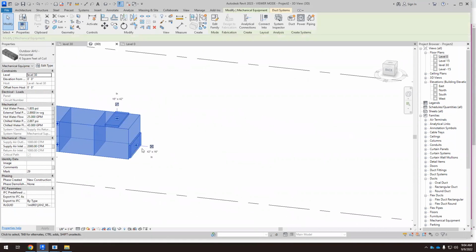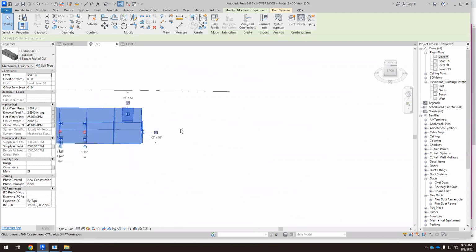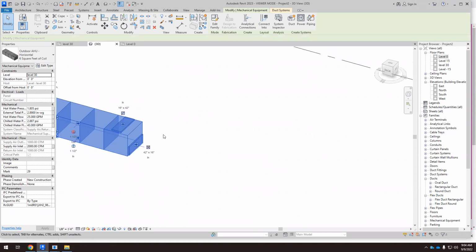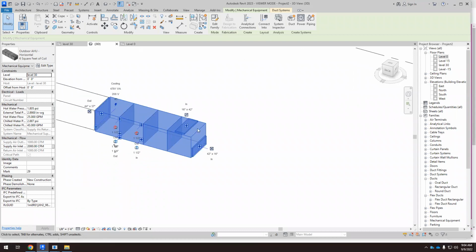You see that here we have two inlets. We have inlet and inlet. This is because in this air handling unit, remember that we need a heat recovery. So in the heat recovery, we need to insert the return air. Then we have the supply air from the outside, the fresh air. Here we have the heat recovery, and then we go through this. I will explain what this is later, and then we go to the supply.